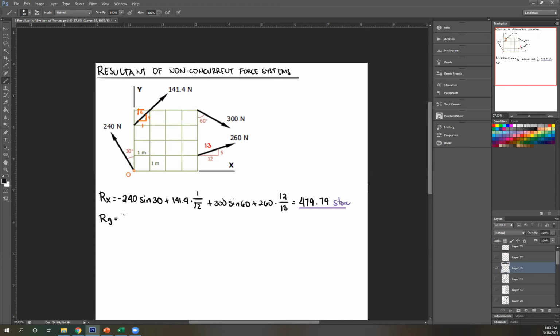Again, let's start here. This is upward, therefore positive 240. I want to take the vertical component, which is this. And that is adjacent to your angle, and therefore I'm going to use cosine, since cosine is adjacent over hypotenuse. Okay, so cosine 30. Once again, to reiterate, x is equal to F cosine theta if theta is from the x-axis. Here, this theta is not from the x-axis, so I'm not going to use that. Or again, if you're used to that, you can just solve this to be 60, therefore 240 cosine 60, 240 sine 60 for this. Okay?